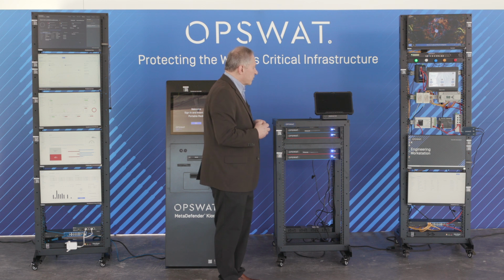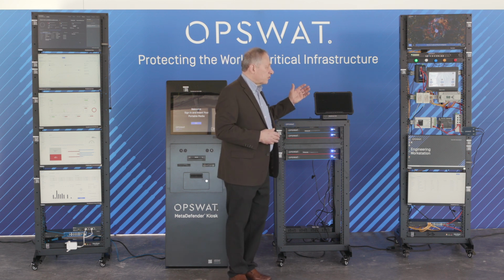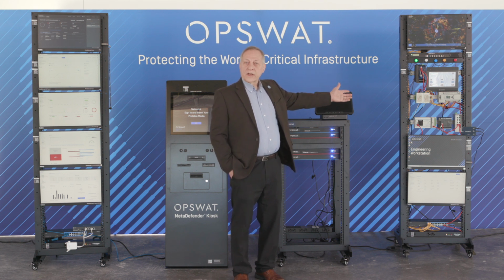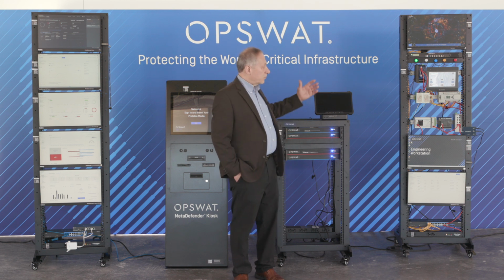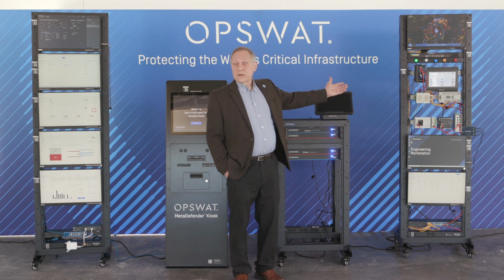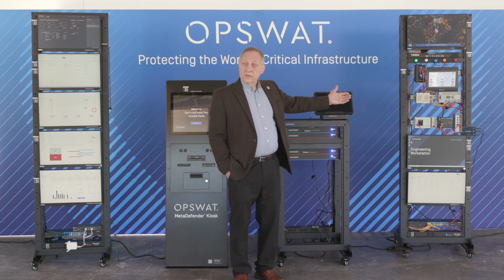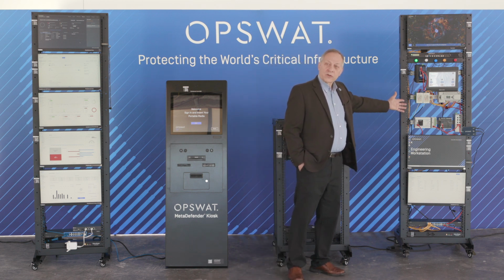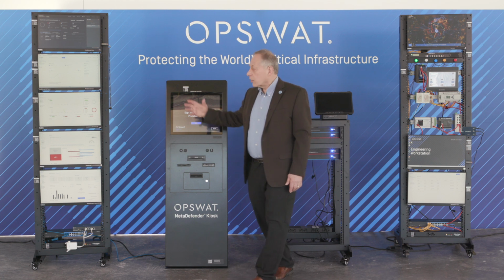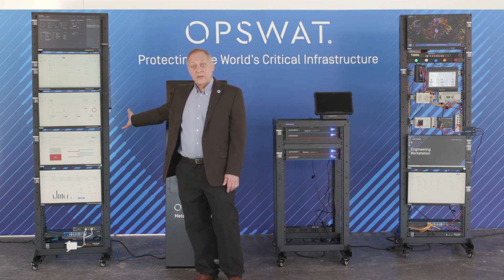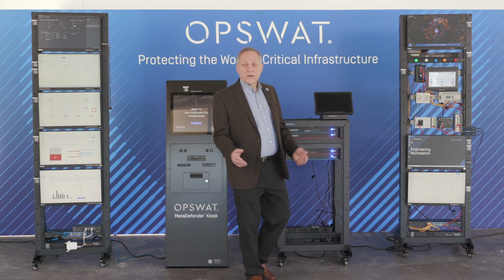So what NetWall can do is transfer syslog, alarms and events, and other data like that to monitor system health. It can replicate real-time operational data using OPC as an industry standard to replicate the tags and the specific values of those tags from the control systems out to a replicate OPC server on the destination side, or the IT side. And it can actually replicate historical data.